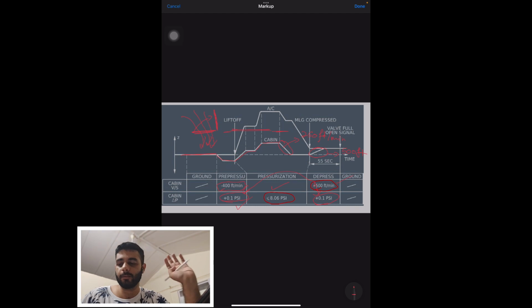That's it. Okay, the outflow valve again opens both ways. Supposing this is the valve, it will open like this. One comes inward and one goes outward. The idea is that if the two flaps open in different directions, depressurization of the aircraft is easier, because it won't matter whether the high pressure is inside or outside; in both cases one of the halves should open easily.